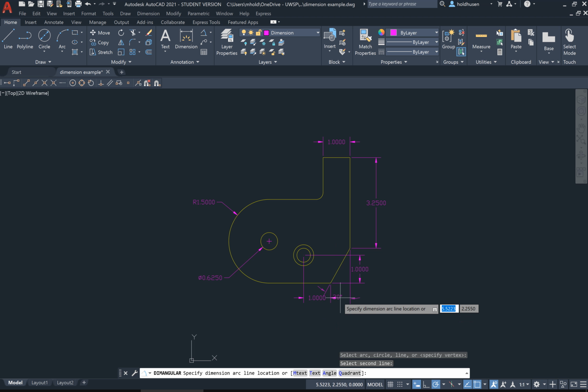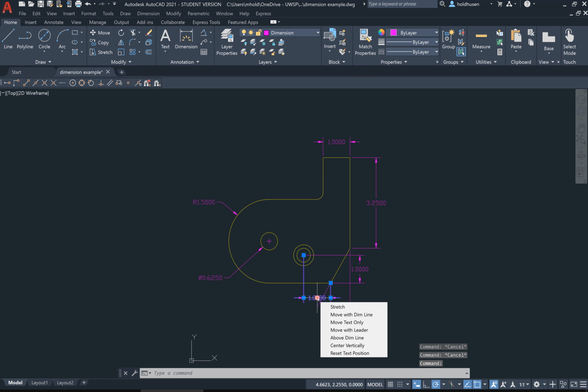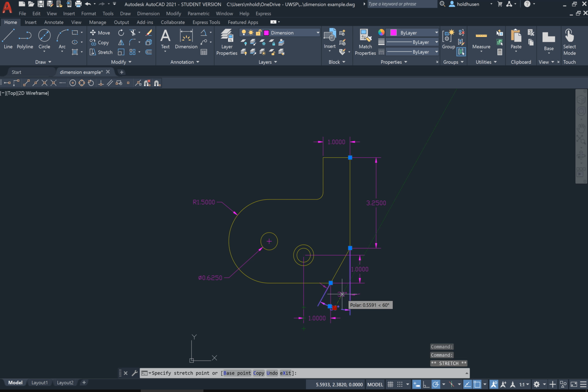Okay, now what I think I'm going to do here is, with that, I'm going to show you that you can then move a dimension, right? And all you need to do to move a dimension, make sure you've escaped out. You can click on this guy, grab in the middle, and you can pull it down and put it where you need to put it. Okay. Again, maybe that's not the best place to put it, but you can maybe move this guy now if you want, and maybe do it like that. Maybe it would have been better to do the 150. Again, it doesn't matter. You can play around. You can move these guys around as necessary. So I think I've shown you most of the dimensions on there.